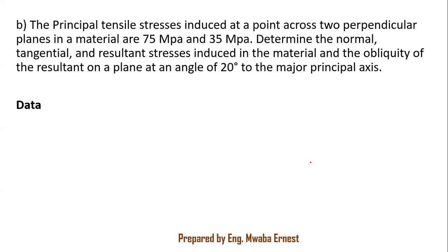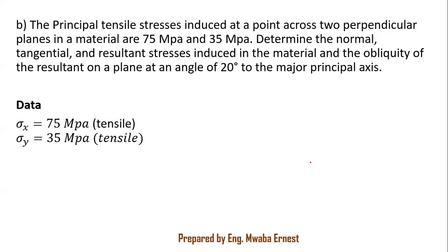Data, information provided. First, stress in the x-axis. Tensile stress is positive 75 megapascals. Stress in the y-axis, 35 megapascals. Then we also have the angle of obliquity before anything, before the action. So theta, 20 degrees.